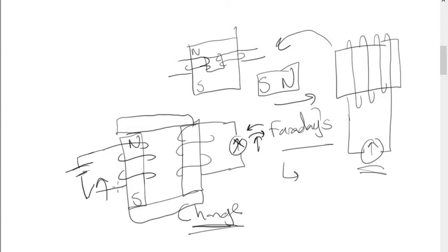Reason হচ্ছে because again when you're opening the circuit, you're causing a change in flux linkage in the secondary coil, right? মানে আগে ছিল কি? When you closed it, it changed from no magnetic field to some magnetic field. So this change induced an EMF. পরেরটায় what's happening is it's moving from some magnetic field to no magnetic field. যখন এই চেঞ্জটা হচ্ছে তখন what does it do? It induces another EMF, but it's going to be in the opposite direction because of Lenz's law. Yes, Jeffrey.